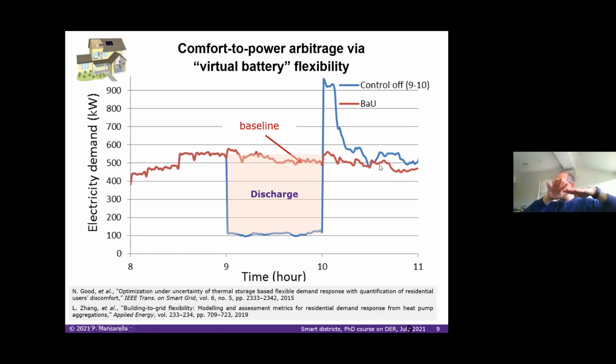Because when you're moving on a relatively flat baseline, especially with modern HVAC, you just keep modulating how much power different compressors and fans need. Instead, if you are a little bit more brutal, switching off, switching on, and controlling your temperature like this, because it's valuable to do so, for example to provide a frequency response service that is needed, then you can have this more extreme variation.